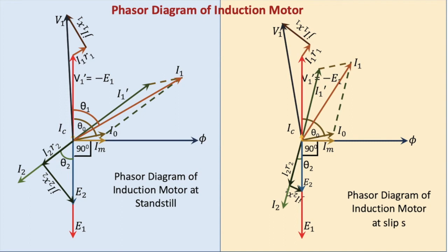Now over here, one more major difference with the transformer is we have not taken the voltage drop because rotor conductors are short circuited. So V2 is equal to 0. We don't have the secondary voltage because the rotor conductors are short circuited. Hence your V2, the terminal voltage, is equal to 0. So your induced EMF is only dependent on the drops in the rotor, and therefore the E2 quantity is quite less. Now this is the angle between your primary current and the primary voltage, that is theta 1. So that can give you the actual primary stator side power factor.